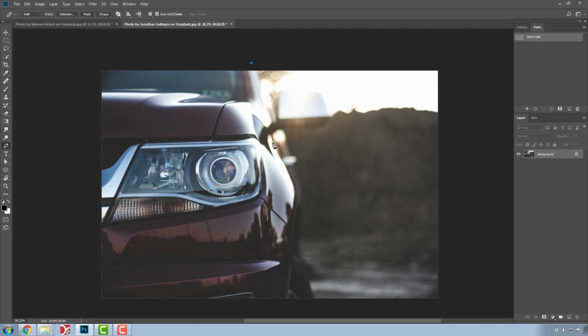We'll show the endpoint, and then instead of letting the mouse button go, we drag the cursor. The two lines that extend from the point are called handles. These handles control the curved line. With Alt, we can control the handles. Hold Alt, and you will see a small break with which you can control the handles, depending on how curved you want the line to be.